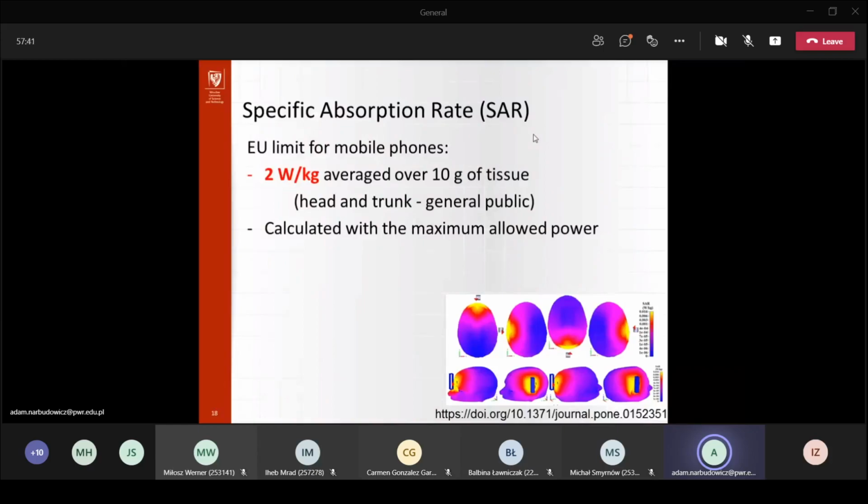A note here is that most of the mobile phone standards use smart adaptive power levels. So typically, especially if you're in proximity to the base station, your mobile phone will reduce the amount of power that it's using, simply because it goes back to the link budget equation that we discussed in the past.